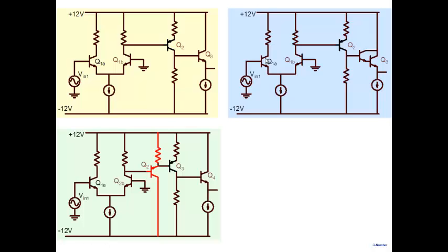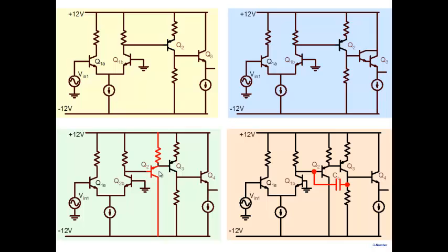There are various possibilities, but we said that another way of handling the output resistance problem was lowering this resistance here and then compensating by putting a common collector stage here. And finally, we saw that almost all the op amps you will build will be unstable. They will give you negative phase margins, and you'll have to have a compensation strategy. This is a very simple compensation called Miller's compensation, which allows you to introduce a dominant pole and thereby obtain a stable amplifier.